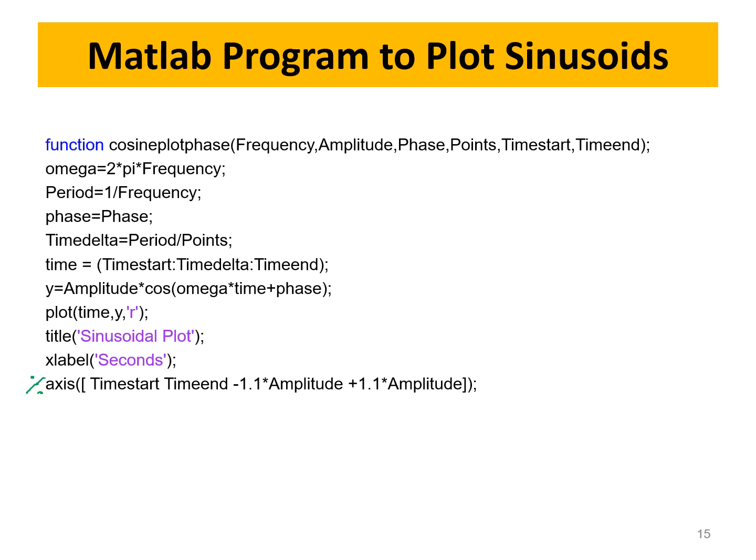So you created the function that plots the cosine with phase for you. You write all of this into a MATLAB file, an M file. That's what we call it. And you name the file with the name of the function .m. When you write this, you save it. After you save it, you go to the command line, and you can call it like this: cosine plot phase, right?